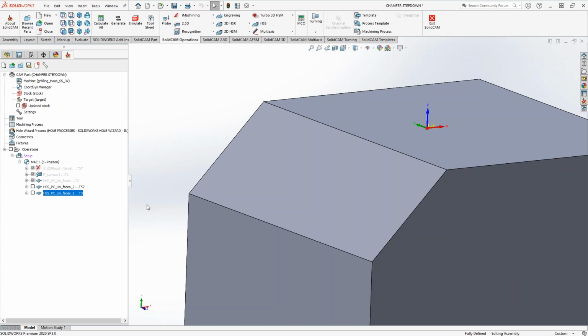I've got to think about that. I think the way that you worded it earlier is a good way to think of it. It doesn't necessarily mean that you can type in an exact scallop height and then get the exact RA value. A lot of times you're going to have to use a more practical rule of thumb with those sort of numbers. So if you have an RA of 32, it sounds like you were saying zeros and a 3.2. And that way you're done, right?